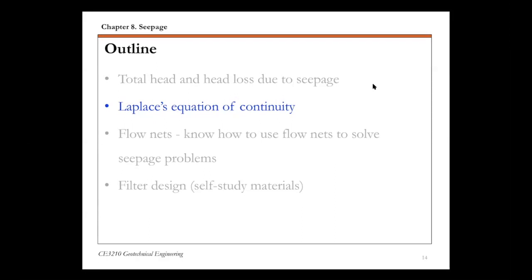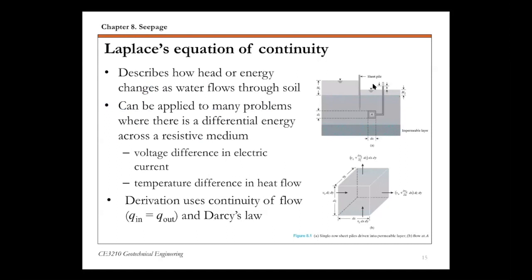So next, we're going to briefly discuss this Laplace equation of continuity. Okay, so first, as I mentioned, this Laplace equation describes how head or energy changes as water flows through soil. And so the Laplace equation is actually not unique to geotechnical seepage problems. It can be applied to many problems where there's a differential energy across a resistive medium.